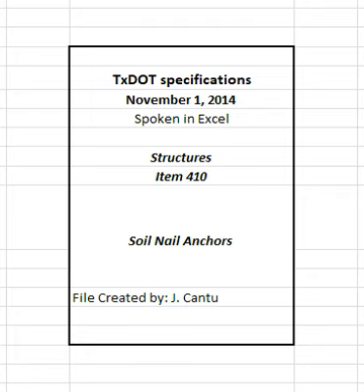4.2 Drilling. Drill the hole so that its diameter is not smaller than the diameter shown on the plans or established by test soil nail anchors. Control hole alignment so that it varies no more than 5 degrees from the line specified on the plans. Furnish suitable drilling equipment and use methods suitable for the ground conditions. The use of drilling mud or other fluids to remove cuttings will not be allowed.